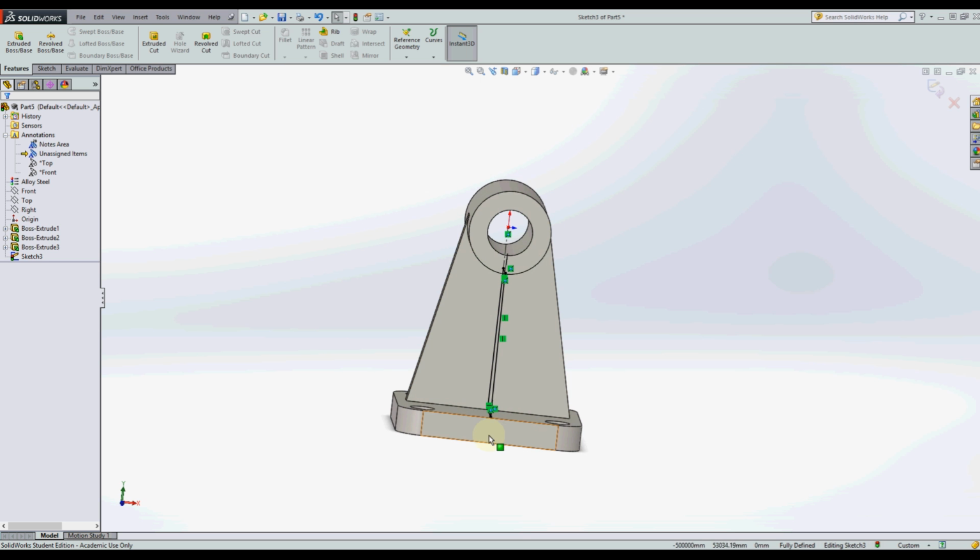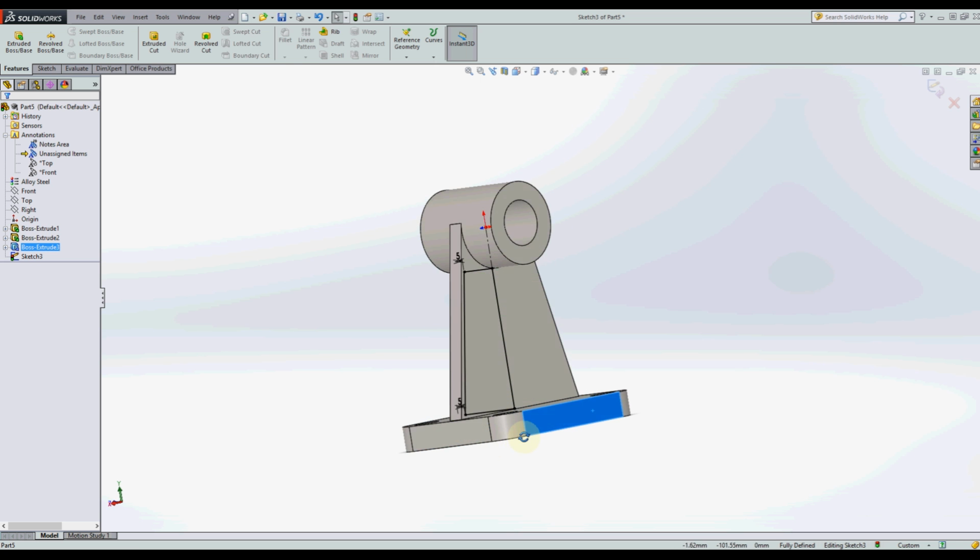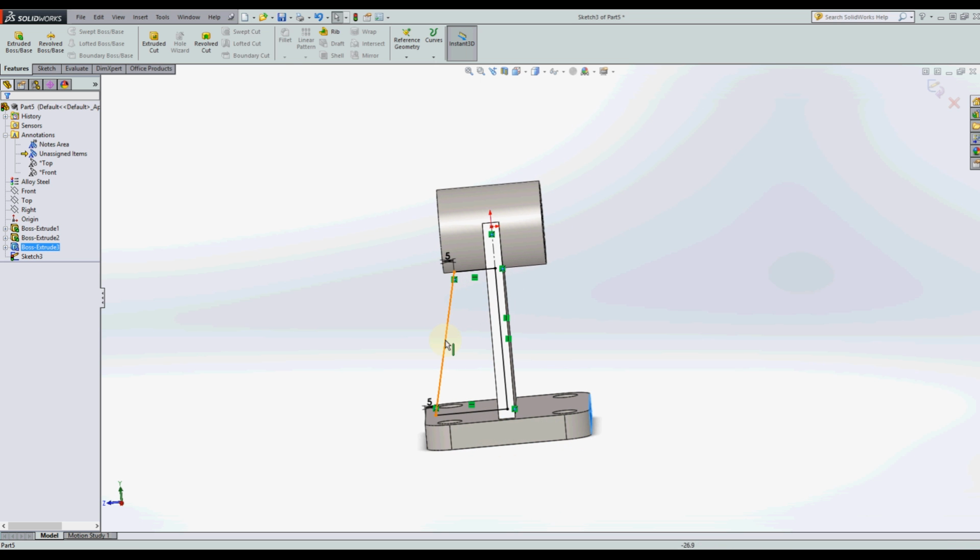And then I would start from this sketch, making an extrude to this side and then cutting away the excess material for the angle here using a cut extrude. So this is also an option, but it uses more features.